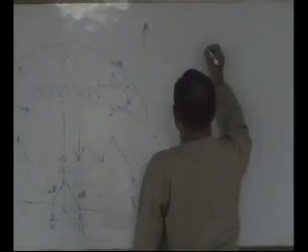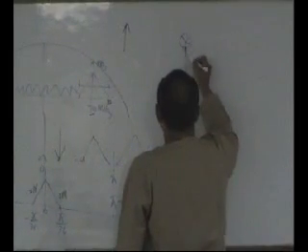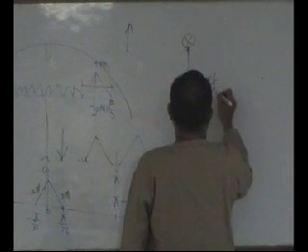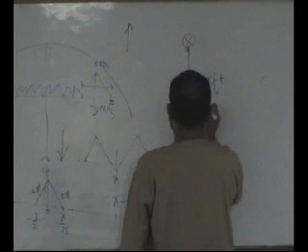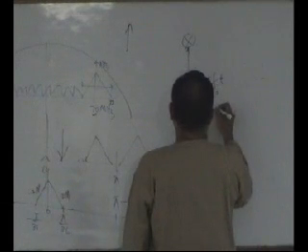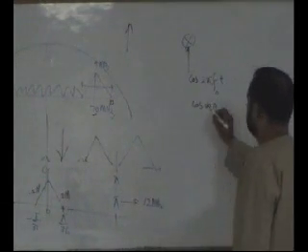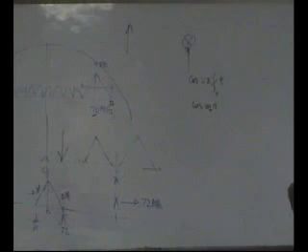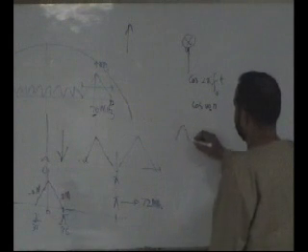To move this up, you need to multiply it with the cosine of 2 pi f naught t, or its equivalent digital form, which is cosine of omega naught n. Okay, this is what you need to do. If you are doing it digitally, and usually we do it digitally, you need to mix it with a cosine which corresponds to a 70 megahertz cosine. And we know how to get a 70 megahertz cosine.